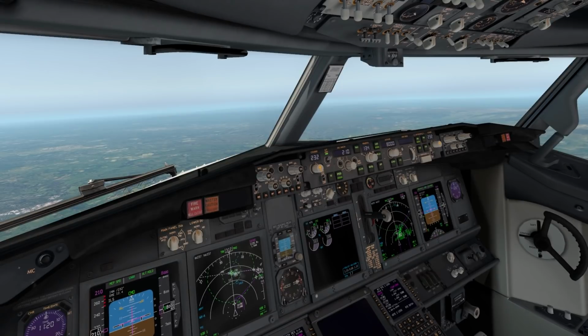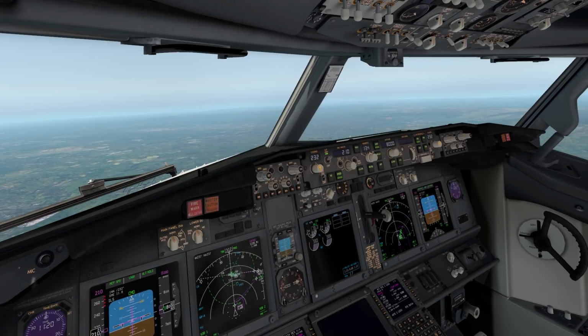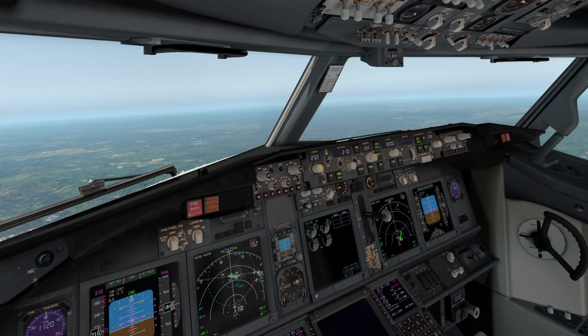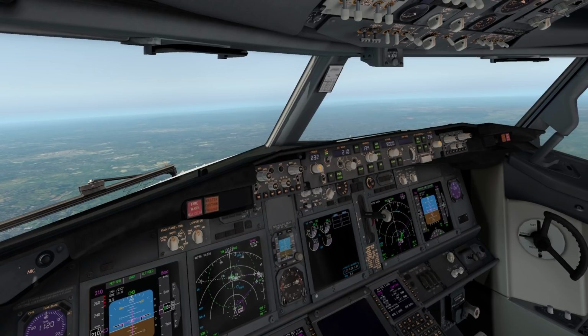So now we've covered the flaps, it's worth noting that flap issues are pretty rare. I've not had any flap issues in the past 10 years operating the 737, but they could happen. Now you've seen how trailing edge flaps and leading edge flaps can be extended using their respective backup systems using the alternate flap extension system, and you'd complete the applicable non-normal checklist to configure the aircraft accordingly. But the odds of not being able to extend any flaps is extremely unlikely.